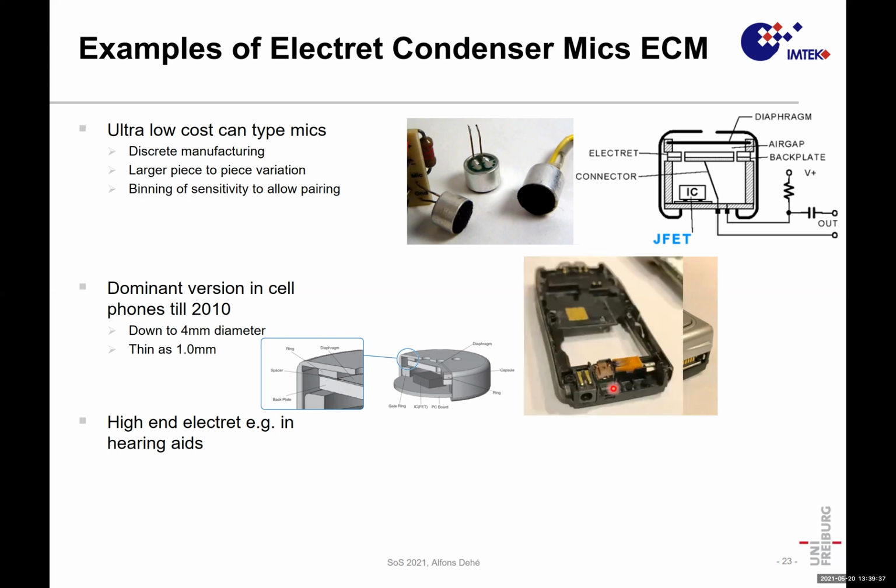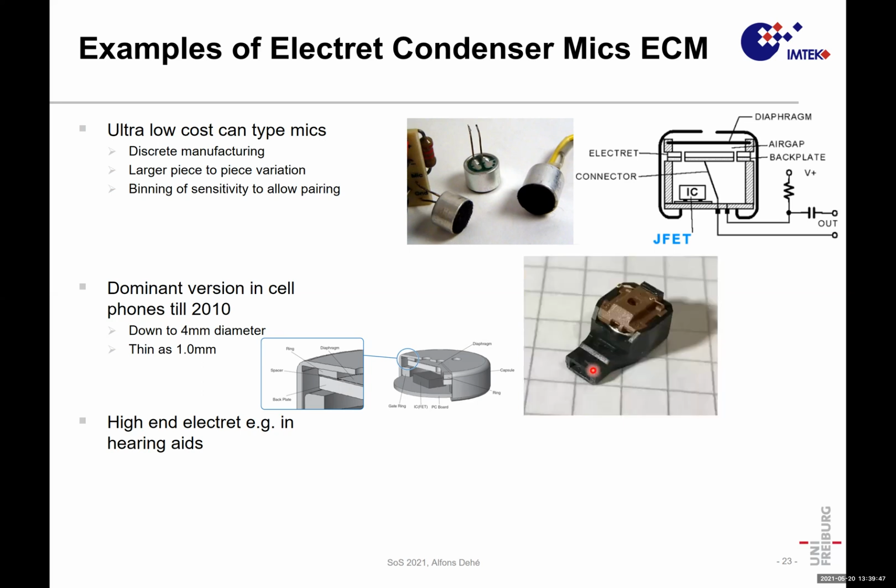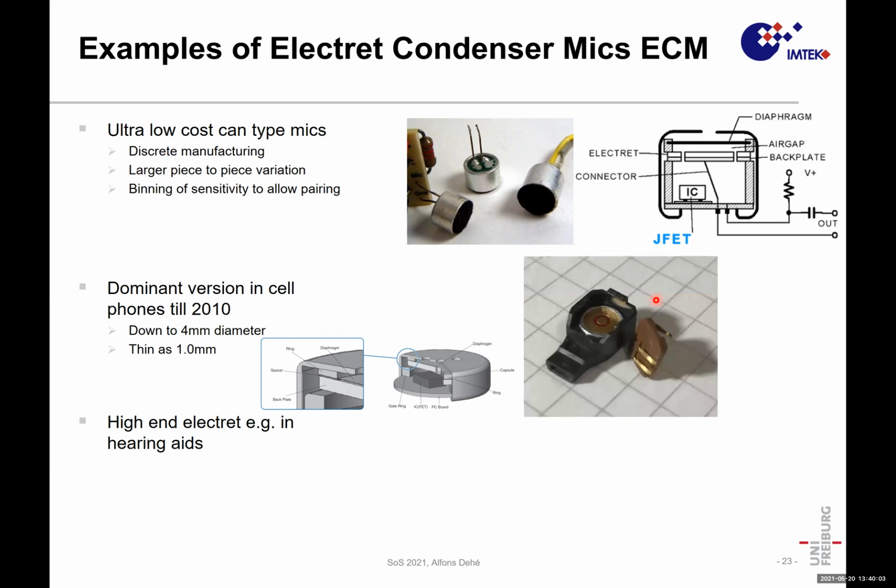If you disassemble this, you find the microphone mounting. It's like a plastic device with some spring contacts. And just to show you how this is applied, I put this out. Here's the sound coming in. This is a rubber device, a metallic device. You see here 2 spring contacts. Why spring contacts? Because if you solder it, you go to 200, 300 degrees C, and you would degrade the performance of the microphone.